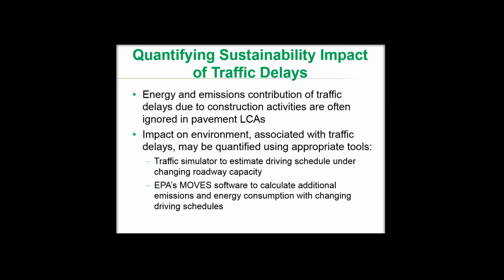Now the question is recognizing the impact of work zone and construction sequencing, and how do we quantify those impacts? We talked about some of the programs that can do this job. Basically, the idea is to quantify the energy and emissions, user delays, and economic impact of construction practices, which will result in traffic delays due to construction activities. And this is a phase often ignored in pavement LCAs because of the complexity of the problem, and we have to calculate the impact on the environment associated with the traffic delays.